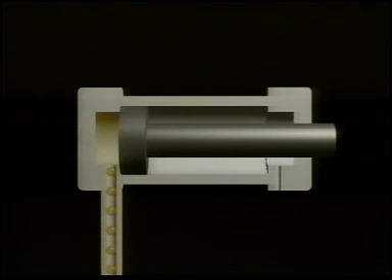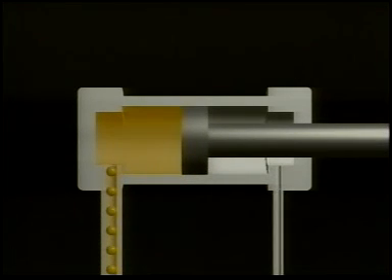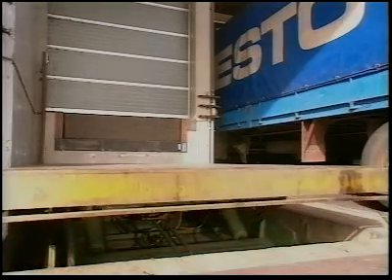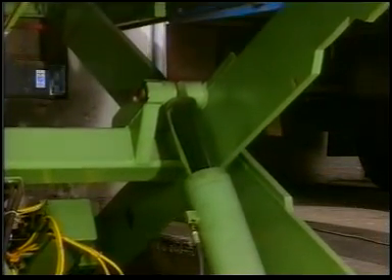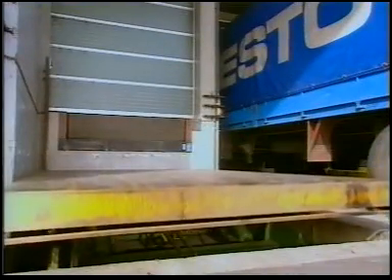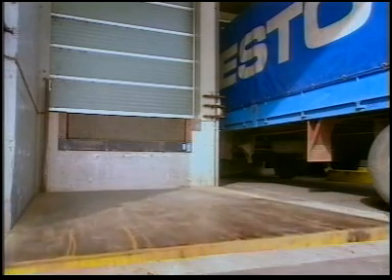Incidentally, the piston doesn't seal off the two cylinder chambers from each other 100%. This is why over time some oil does get into the unpressurized chamber. This oil then flows back to the reservoir via a leakage oil line. Here we see a single-acting cylinder in a scissor-type elevating platform. The return stroke is powered by an external force, in this case the weight of the platform.